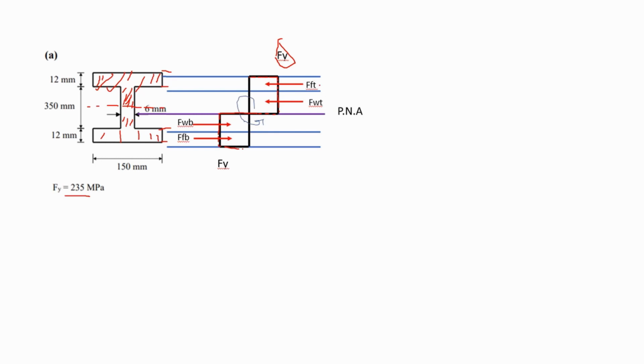So as you can see, I have these 4 forces, and in order to calculate the plastic moment, I have to consider rotation about the point where the forces change from compression to tension, at the plastic neutral axis over here, where it reaches 0, as indicated by the blue arrow.